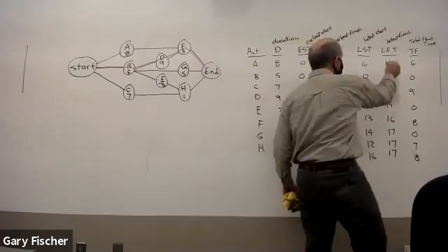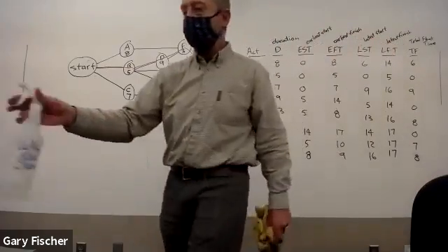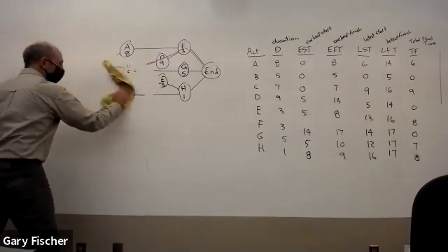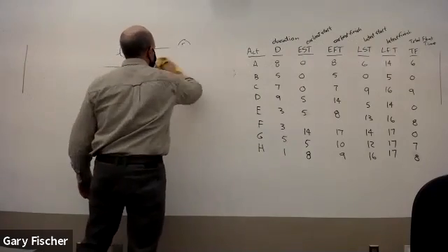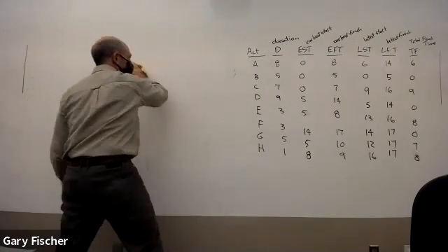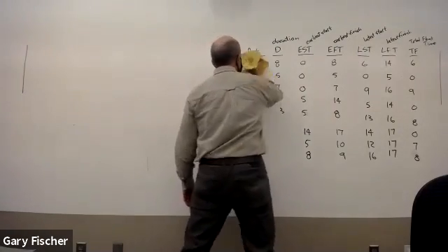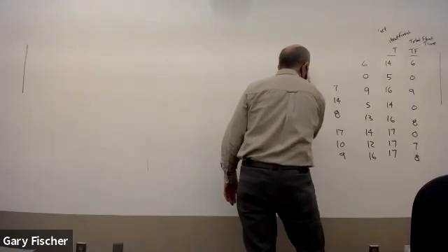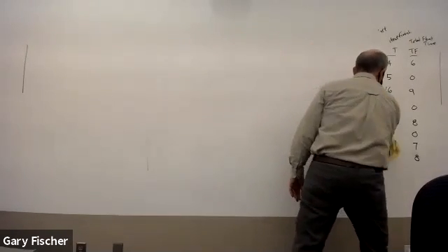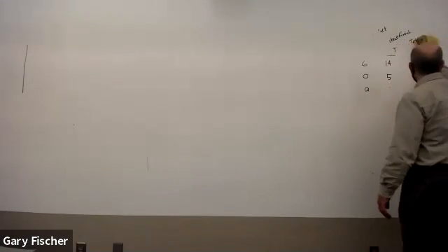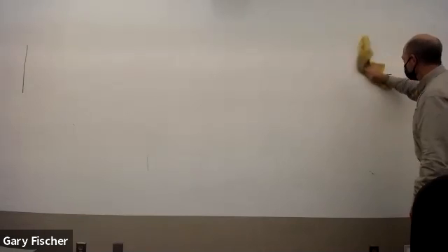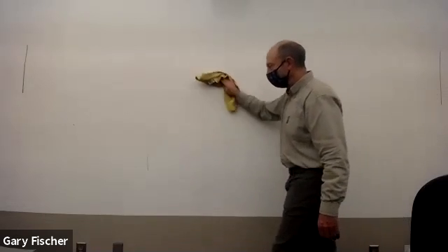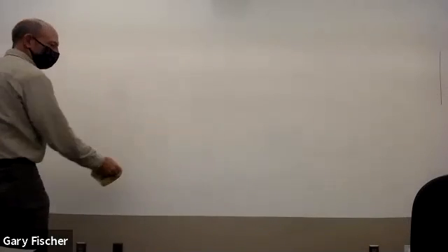A lot of what they use is like the average end area method to calculate volume of cuts and fills. They might throw a real odd thing, and I can't remember what they said. There's one in there that says use the Simpson rule or something like that. I'm pretty sure you could find that formula in the reference manual, but I didn't know it offhand. Most of the time, they're fairly straightforward types of calculations.